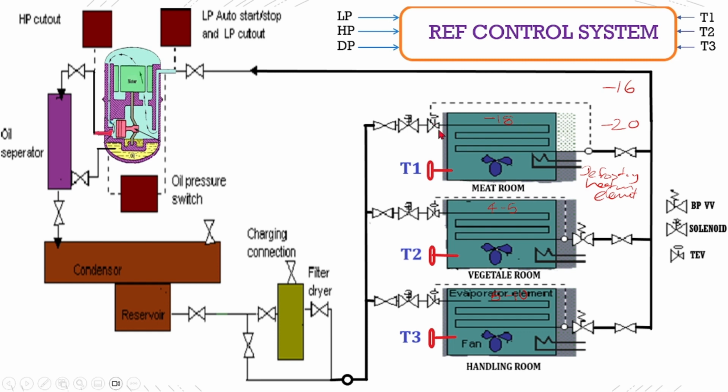And the expansion valve, the purpose of the expansion valve, we know already, it acts as the variable orifice depending on the temperature at the evaporator outlet, it varies the flow. So it sends the evaporator outlet temperature through this bulb and its sensing line, and it adjusts the flow. So the pressure drop will take place, and hence the boiling temperature will lower, right?